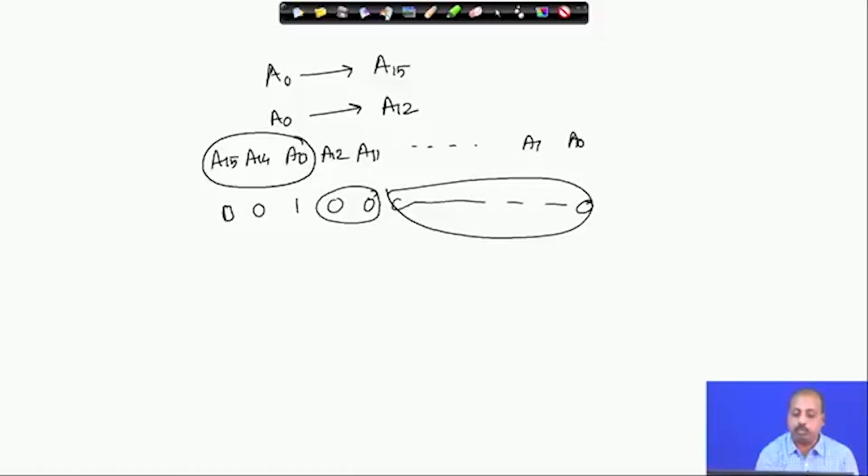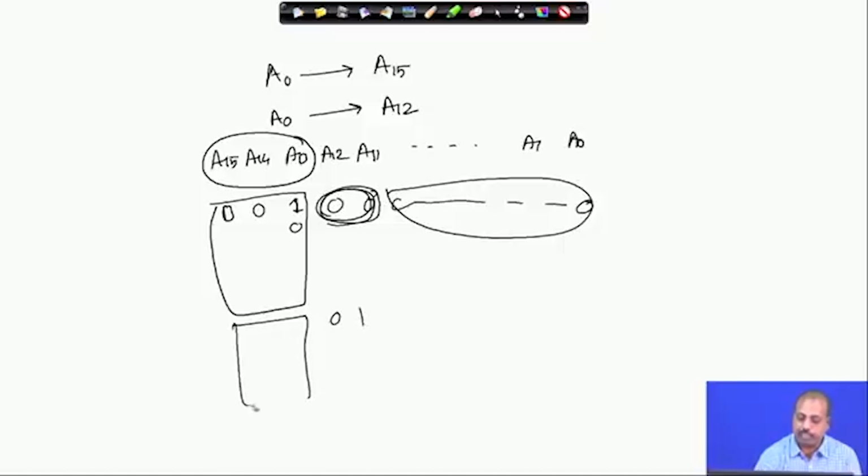So, that is what is happening. If this bit is 1, then it is actually the same memory that gets accessed compared to the case when this bit is 0. Similarly, whenever A11, A12 is 0, 0, whatever the values of these 3 bits, it will map to the same memory chip. Similarly, if these two values A11, A12 become 0, 1, whatever the values of these 3 bits, they will get mapped to the second memory block that we have got.